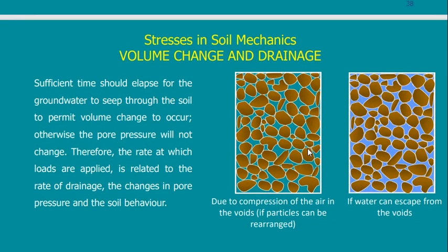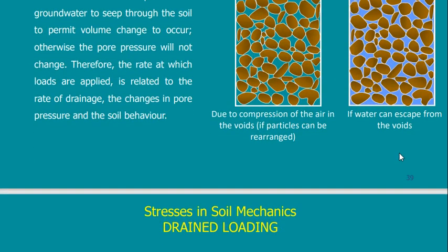This is the only difference. So what will happen is that particles will come closer to each other and try to push, first the voids, then once it finishes the voids, it will start pushing the water in the voids till it reaches a condition where all the particles are stuck together and I don't have any more voids that can be expelled out.